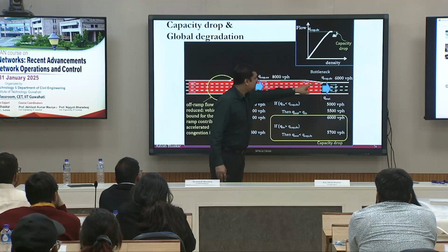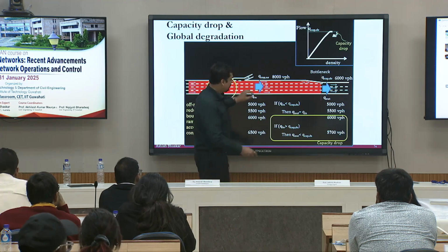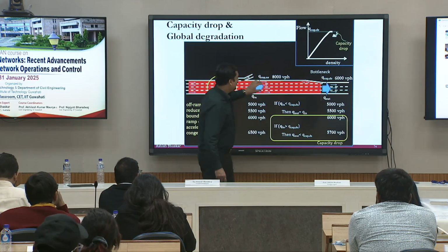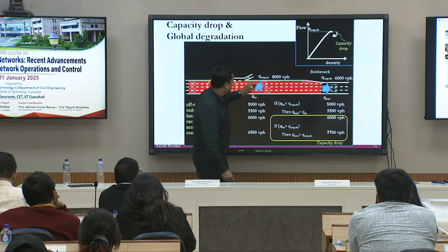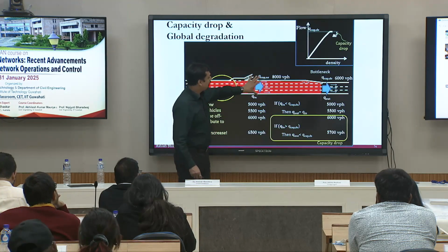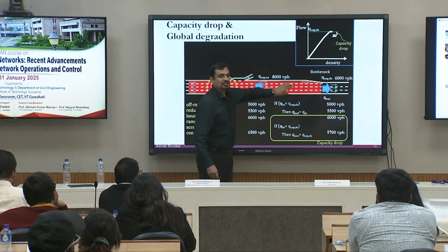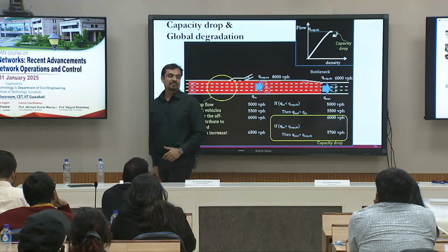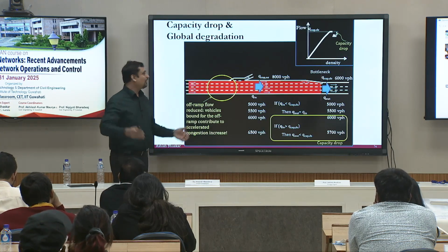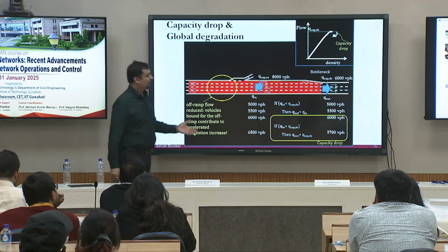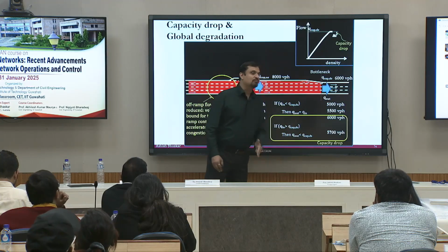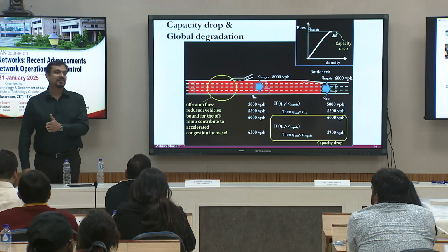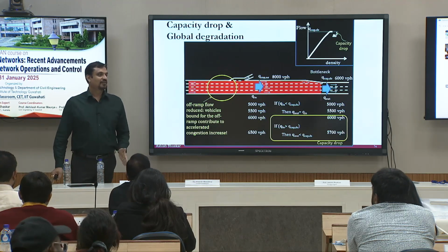Even if there is no queue, let's say in this example 5500, 5500, it will never happen. 5500 is less than 6000, but that 5500 was spread, and when they are approaching here, they have to do the lane change. And the lane change, as you have mentioned, is a reason for congestion. Any abrupt lane change is going to create shocks. So it is a natural bottleneck. Some portions of the road network where we know there is a drop in capacity are natural bottlenecks.